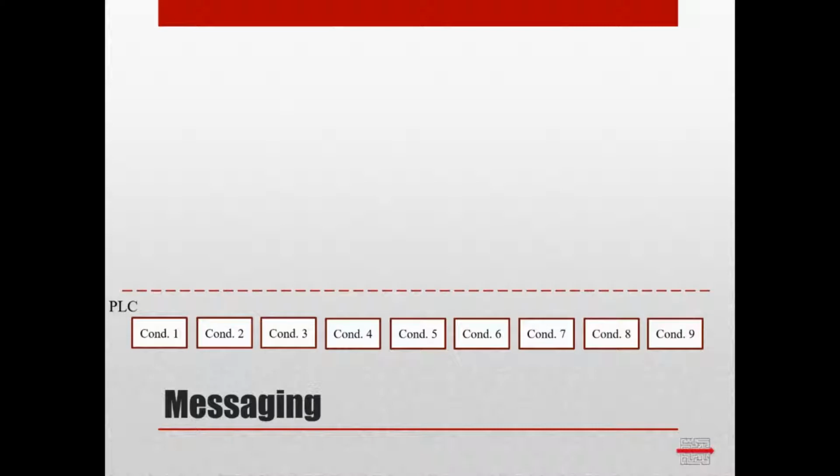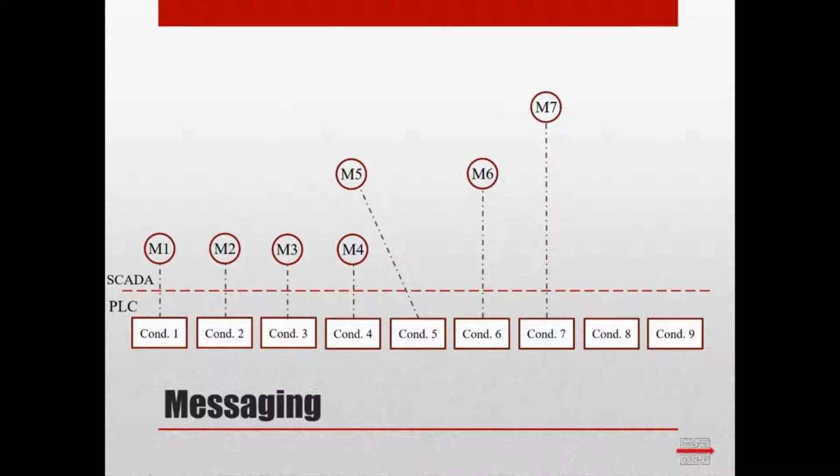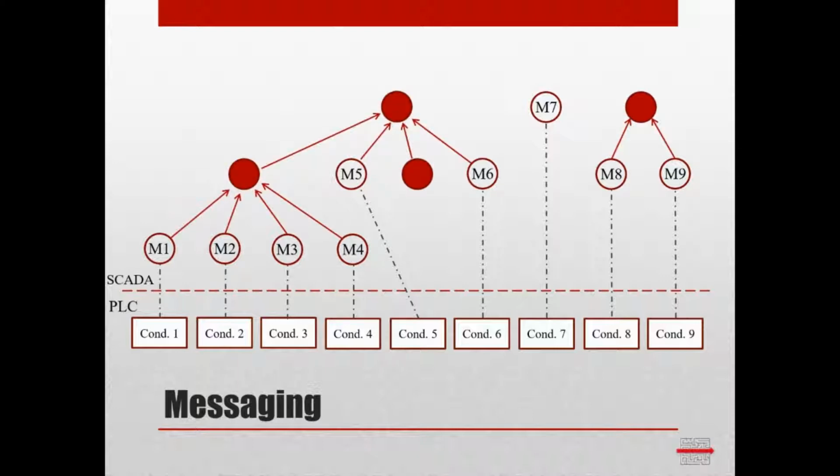Messaging. In conventional DCS and PLC-SCADA systems, based on a condition in the controller or the PLC, a statically configured message is displayed to the operator. It's up to the SCADA engineer during the project phase or during changes to group and order the structure and mask out alarm messages so they're being presented in an unambiguous way to the operator.